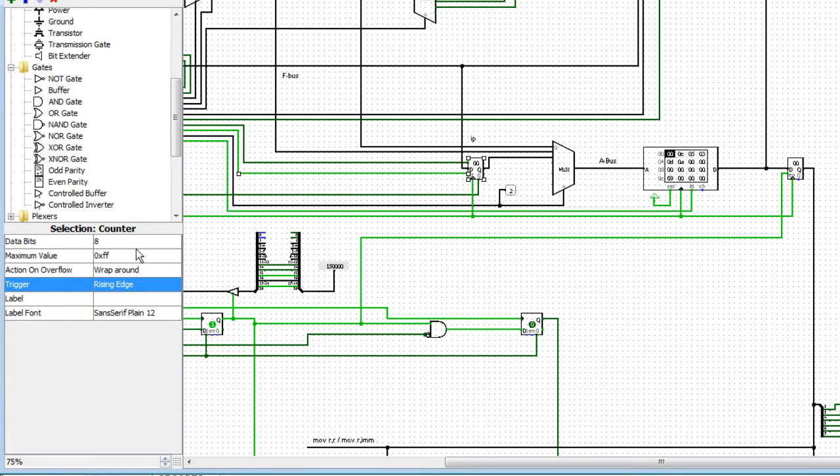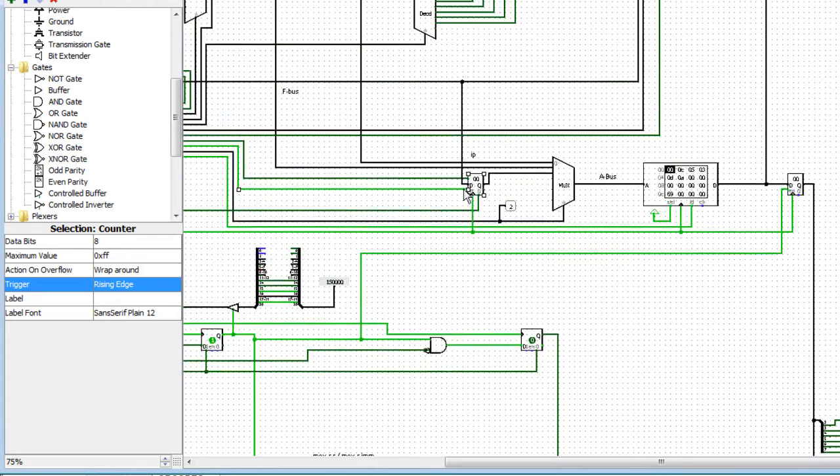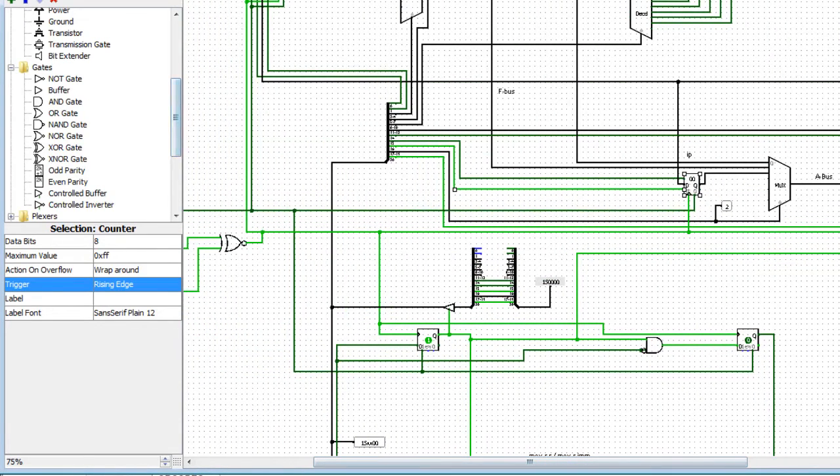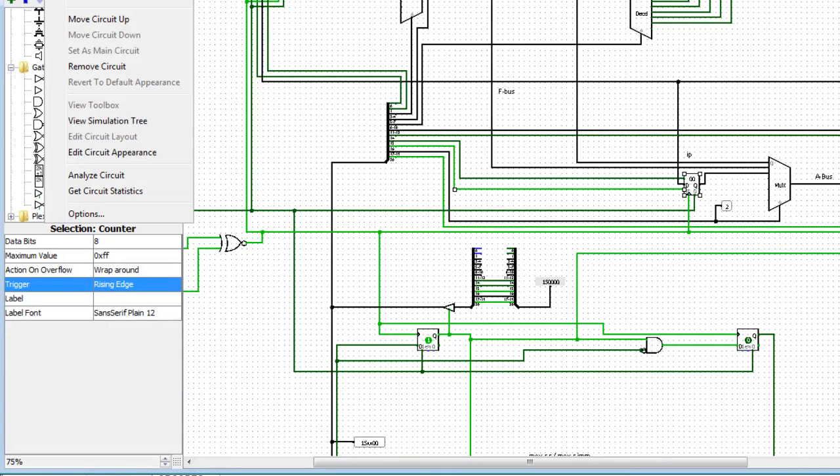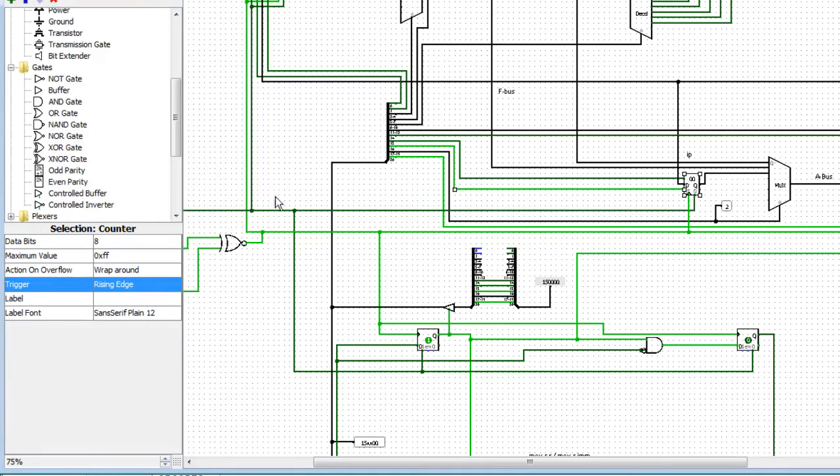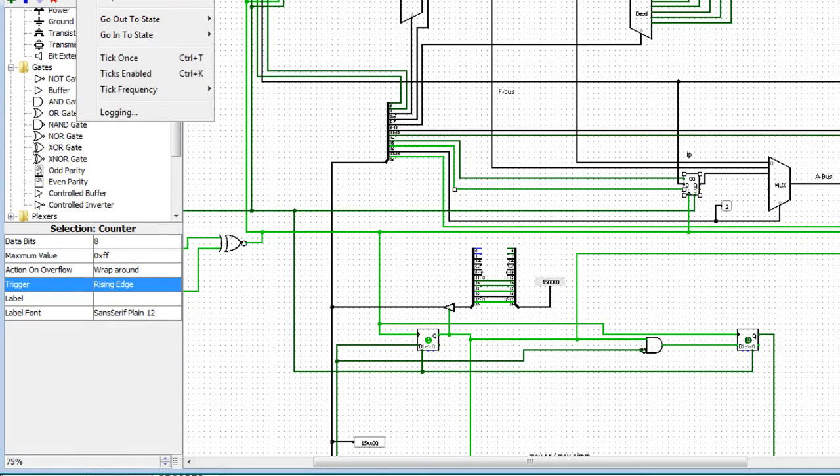So the question then becomes, how do we do this? And the answer to that question is we're going to cheat. We're sort of cheating. Not really. But generally what I might want to do is have two clock signals. One clock signal that runs the entire circuit, and then another clock signal that's running at twice the speed, and that only drives, for example, the instruction pointer. And CPUs do run like that. The internal logic areas will run at higher clock speeds than the external clock speed.